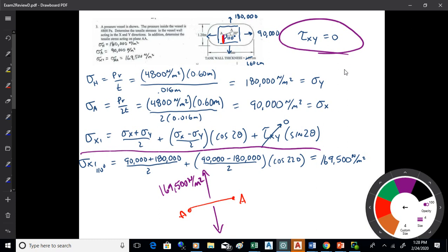What's that now? The pressure on the vessel is positive. Yeah, it's like a balloon. Yeah, it's all positive. Pressure tanks by definition are all positive tensile stress in there. I've had people ask me about submarines and the design of that, if they're the opposite of pressure vessels. I'm not quite sure it's that simple, but maybe they are. They'd all be compression, of course. And that's come up a few times in class. But yeah, these are all tension. They're pulling apart. What's the maximum normal stress in that tank wall? If you're going to design the tank wall, what do you design it for?